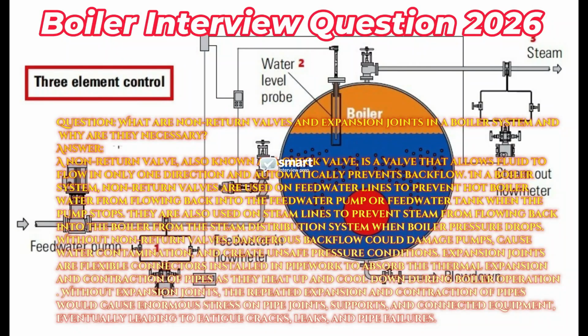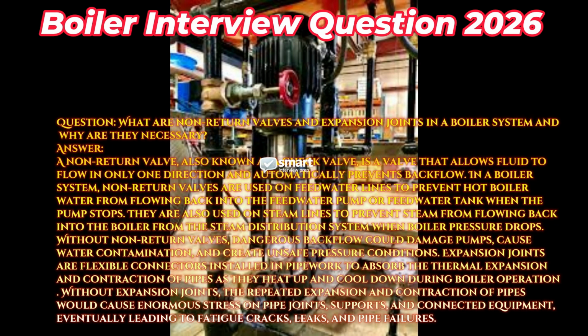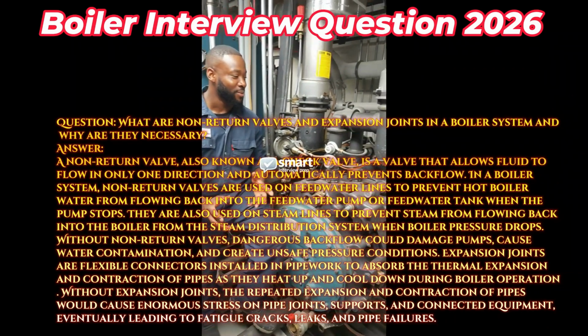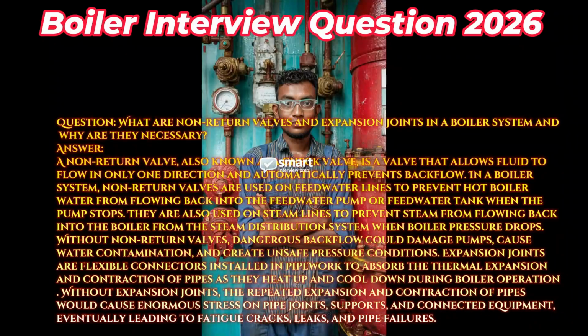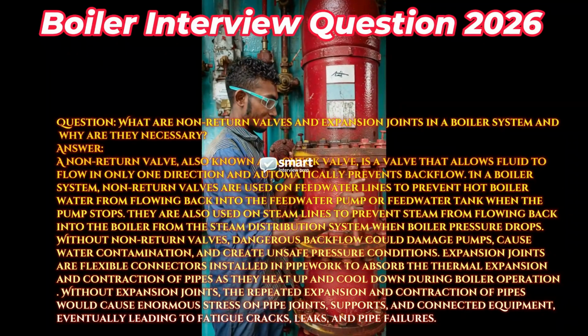Question: What are non-return valves and expansion joints in a boiler system and why are they necessary? Answer: A non-return valve, also known as a check valve, is a valve that allows fluid to flow in only one direction and automatically prevents backflow. In a boiler system, non-return valves are used on feed water lines to prevent hot boiler water from flowing back into the feed water pump or feed water tank when the pump stops.